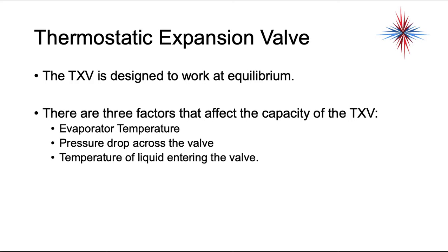There are three factors that affect the capacity of the TXV: the evaporator pressure, or the evaporator temperature, the pressure drop across the valve, and the temperature of the liquid entering the valve.